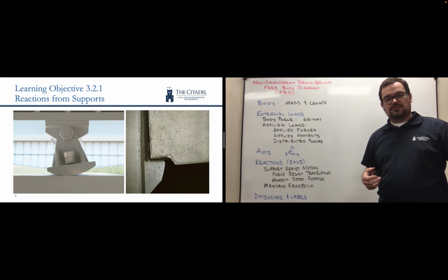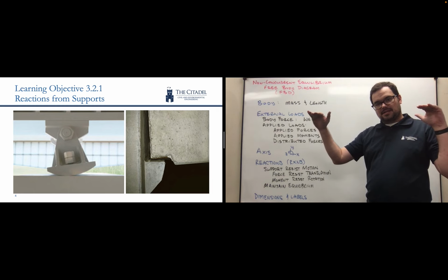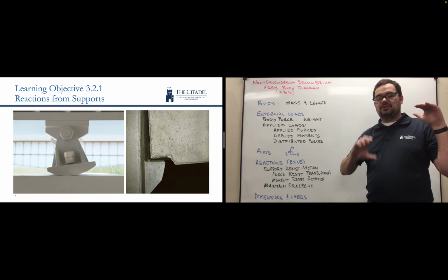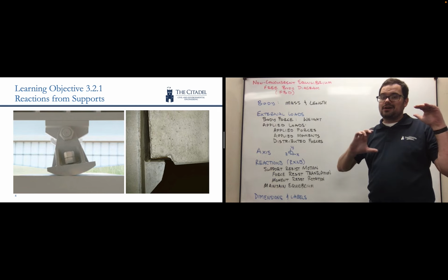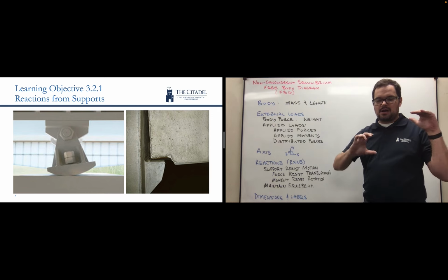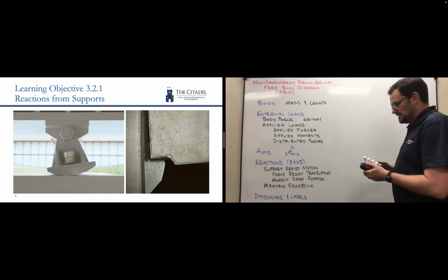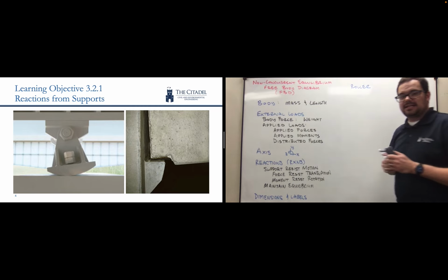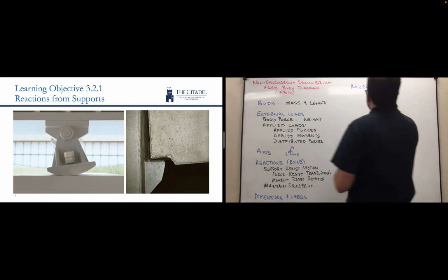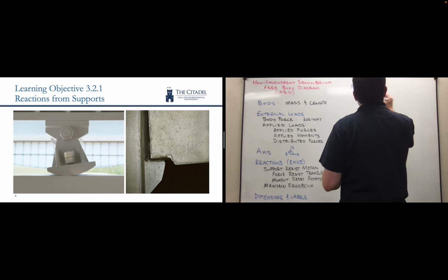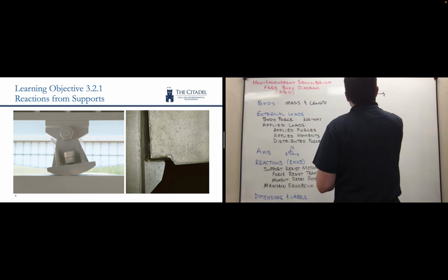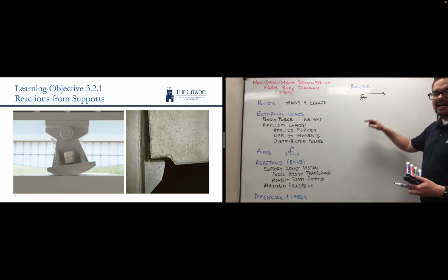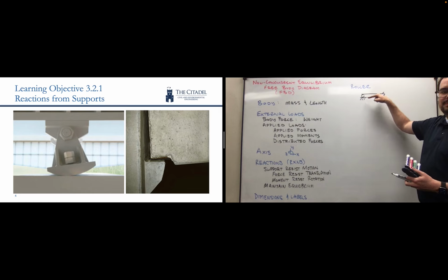On this leftmost picture, you'll see the beam acting across the top, and it's connected to the buttress by what's called a rocker. If we look at a rocker, we might draw it this way. Sometimes it's called a roller. Schematically, the way we draw this roller is like this, where we have the idea of a board sitting on a soup can.